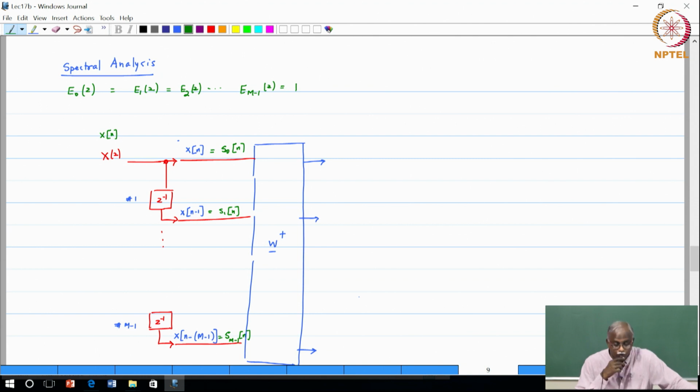Now, what we are computing is like the inverse DFT, but I do not want to call it the inverse DFT because then we start getting confused between time and frequency domains. It is a transformation of this S vector into another vector, an orthogonal transformation, and let us call these outputs x0, x1, x of m minus 1, okay.